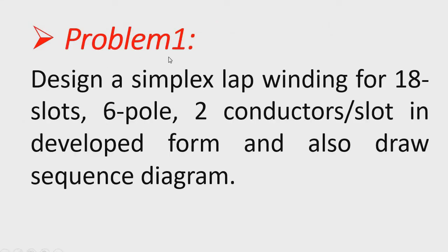So problem number 1. Design a simplex lap winding for 18 slots, 6 pole, 2 conductors per slot in developed form, and also draw sequence diagram. So this is our problem statement.